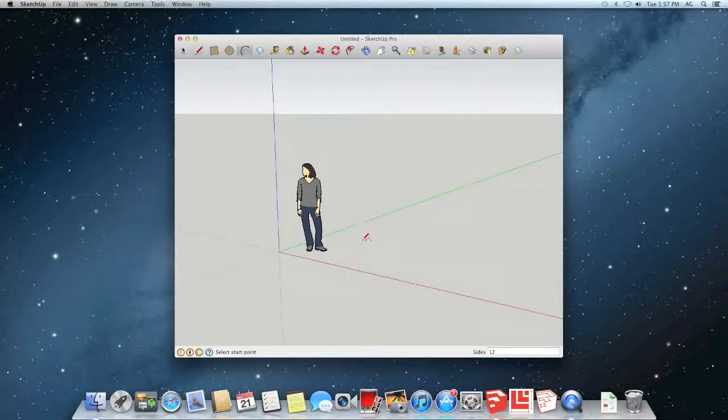The next is to make a component in your model. You will not use this much. It's for accompanying this Select tool where you can make individual items in your model. You can use the tape measure to measure distances between 2 points. Paint bucket is to add various textures and colors as representations in your model. The next tool is the Push-Pull tool for making flat shapes into three-dimensional objects.